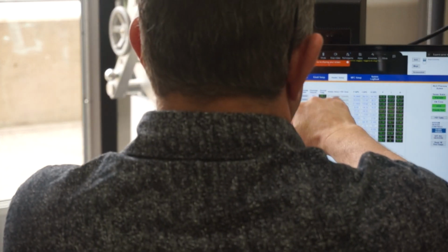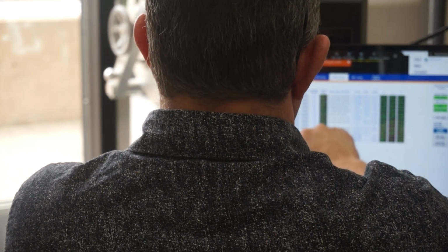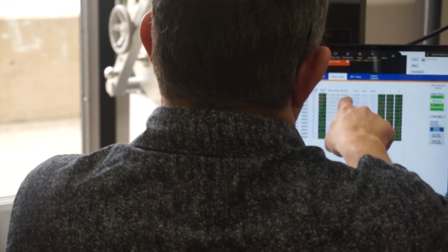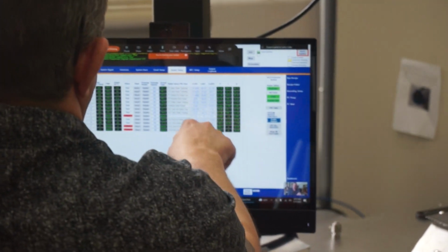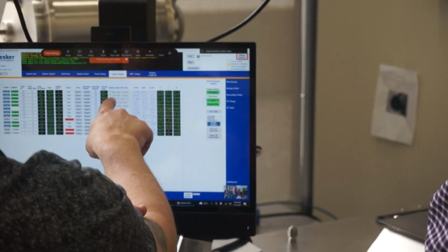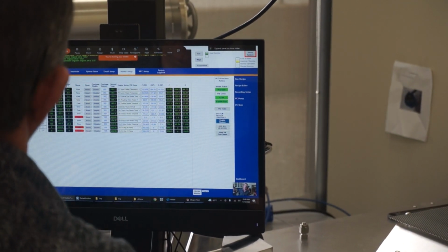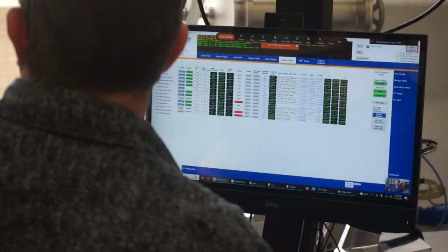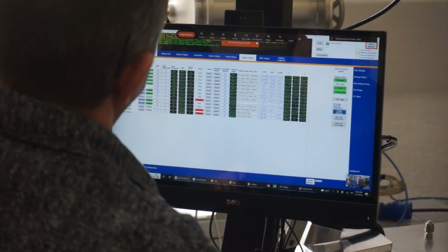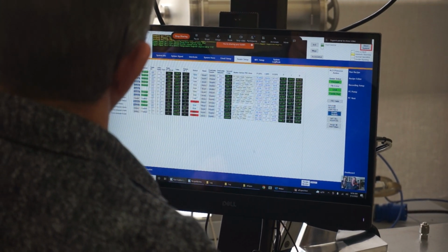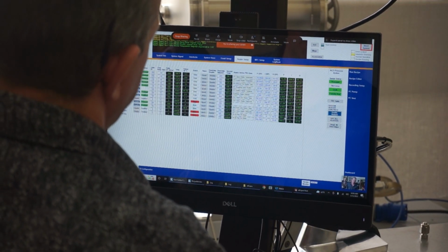On here, there are our PID zones that you can call up. Most of them have a name that corresponds to that heater. It's already set. These are the PID values, and this is what's possible. So we don't need to change it. You won't have to change them. They're already set to tune. If we get into really weird temperatures, we might change that a little bit.